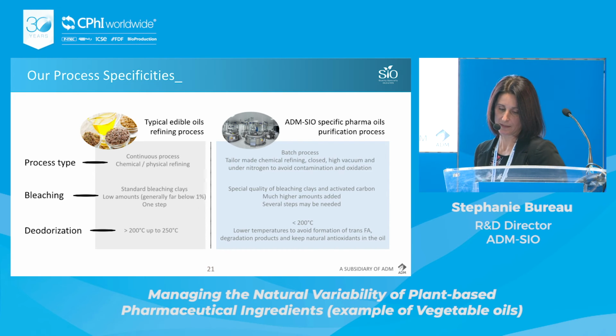And these processing aids are used in variable quantities depending on the nature of the oil and the compounds to be removed. We also adapt at this step contact time and temperature to adjust depending on the type and composition of the oil we have to treat.